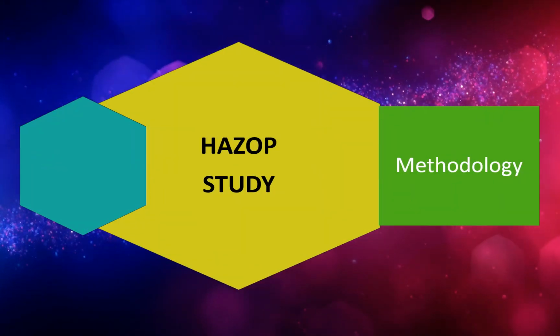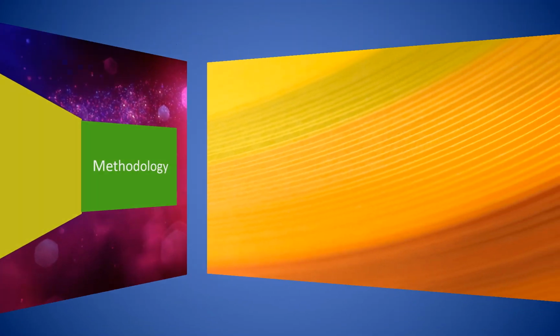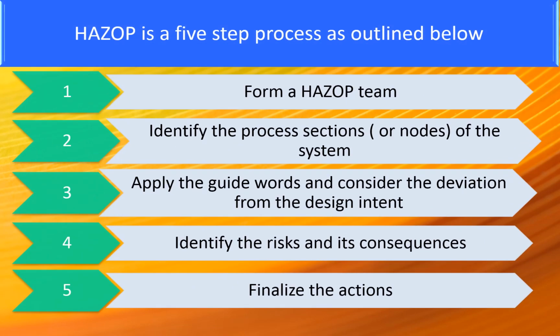HAZOP study methodology. HAZOP is a 5-step process as outlined below. Step 1. Form a HAZOP team. Step 2. Identify the process sections of the system. Step 3. Apply the guide words and consider the deviation from the design intent. Step 4. Identify the risks and its consequences. And step 5. Finalize the actions.